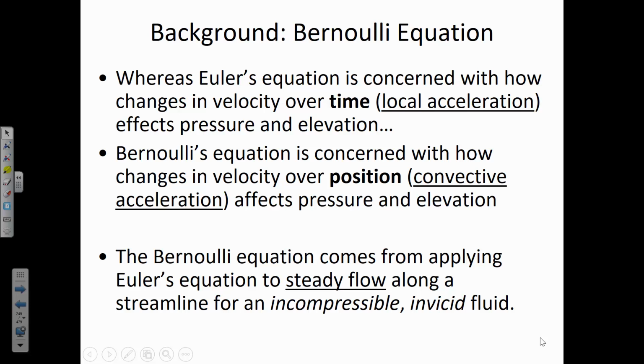So the way that we get away with applying this for fluids that do have viscosity, like water, is if location 1 and location 2 are relatively close together, then the effects of energy loss are minor. And then it doesn't matter so much that the fluid had viscosity.